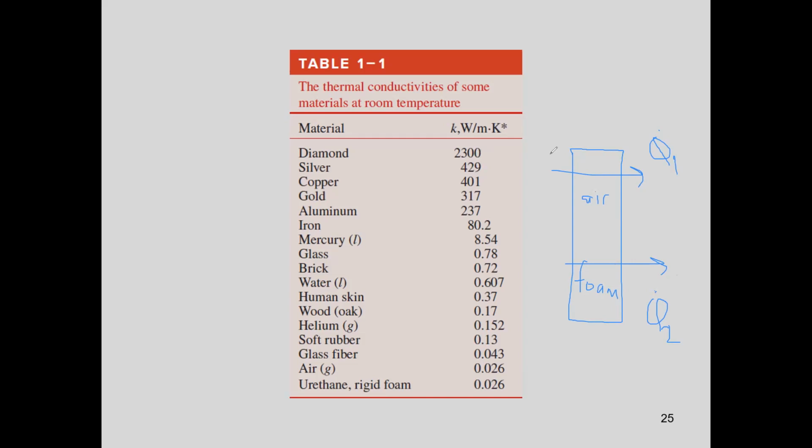Okay, I have some answers. Some people say air, some people say the same. Okay. So the temperature on this side of the wall and this side of the wall is the same for the case of air and foam. Okay, the correct answer is this. There is a higher rate of heat transfer when it is air than foam. Why? This is the answer. There is more rate of heat transfer when the wall is filled with air rather than the wall filled with foam.